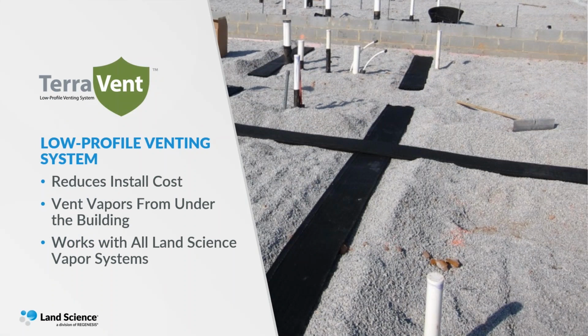Complementing that, we also have our TerraVent. It's a low-profile venting system that reduces the install cost. So before the MonoShield is installed, you can install this Vapor Vent and TerraVent, and the venting system itself will provide that solution of a preferential pathway for the vapors, but it also can be used in an active venting system as well. We encourage that you work with the Land Science team as you're deciding to design a TerraVent system, and we'd be glad to provide our slew of details that we have already previously provided of non-site specific, or we can work with you on site specific layout systems as well.